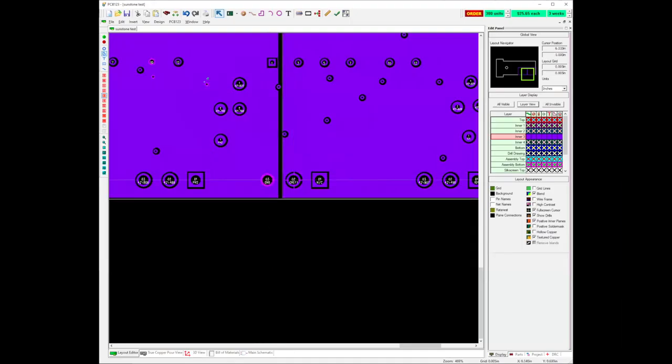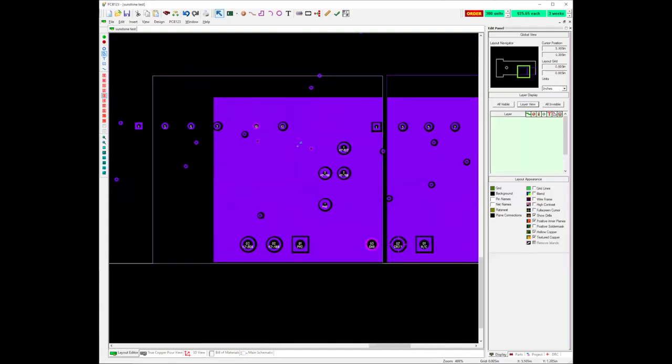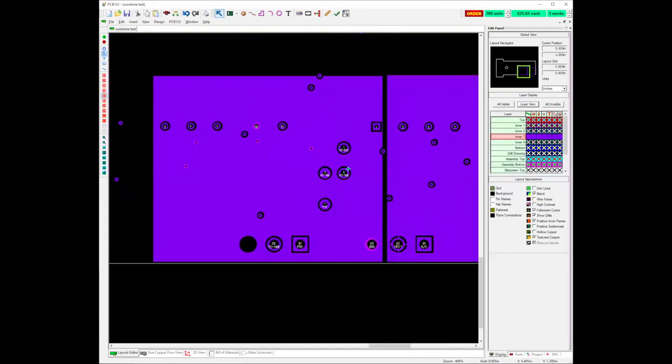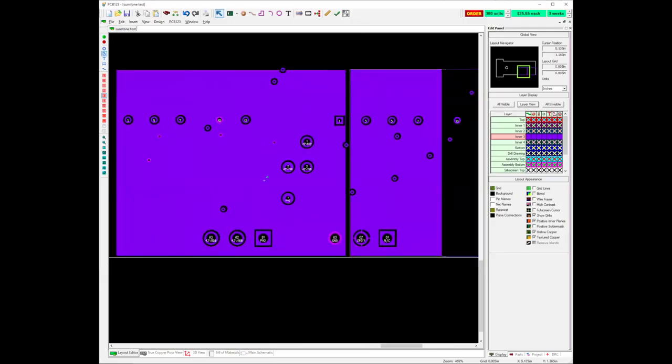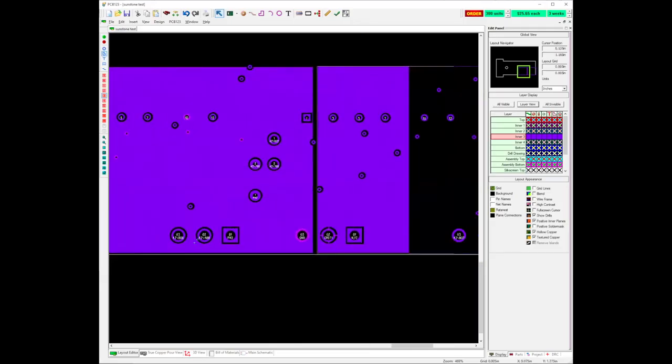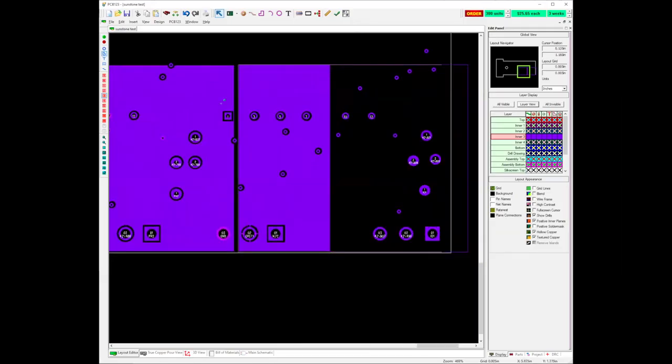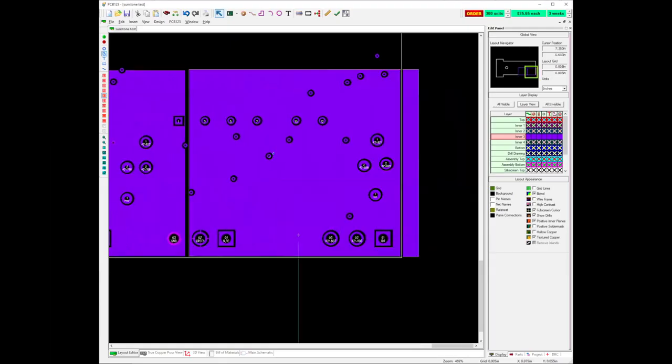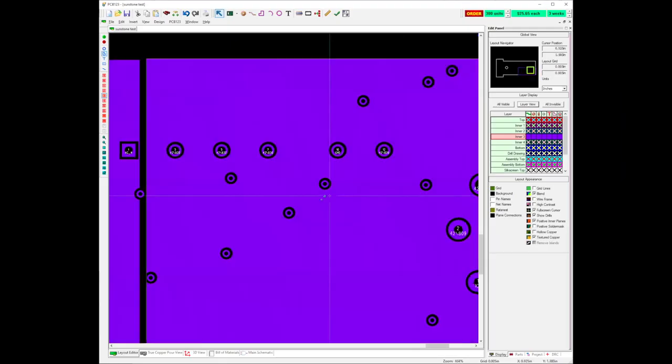And you can see that ground pins are highlighted where they're attached to that plane. They weren't in the negative plane layer that was generated, or with the power layer that was generated. And over here, I've got GREF1 that's connected here. But if there are any ground pins, and there are, they're not connected.